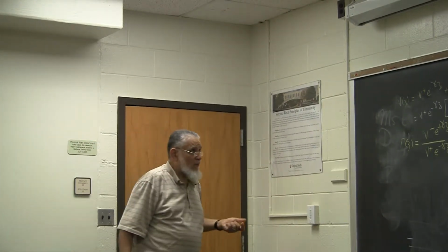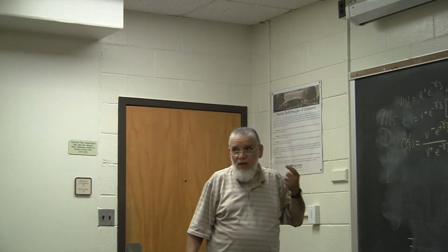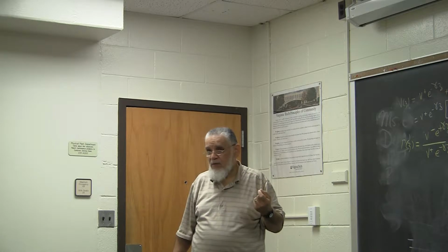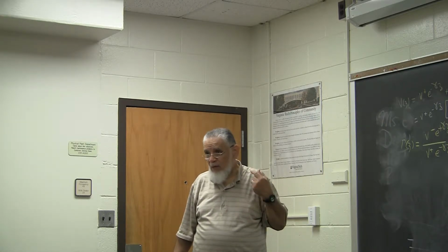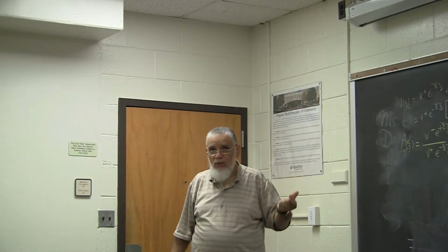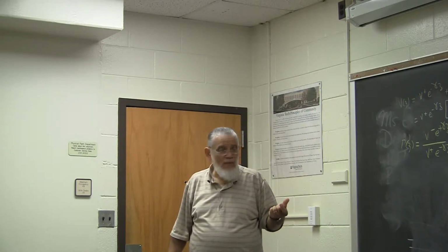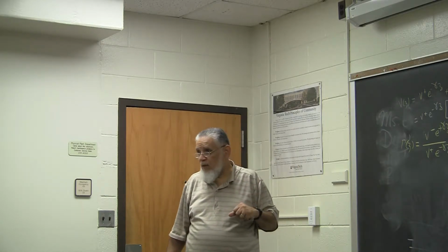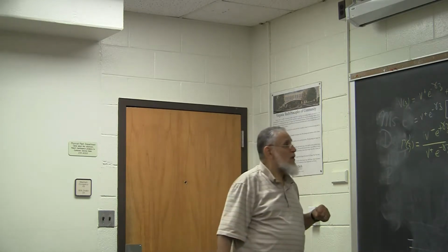Okay? Obviously, if there is another source there, the labeling of reflection coefficient would be kind of inaccurate, because the wave coming back would be partially because of the other source and because of the reflection. All right? But in case of one source, this labeling here brings in that physical insight.